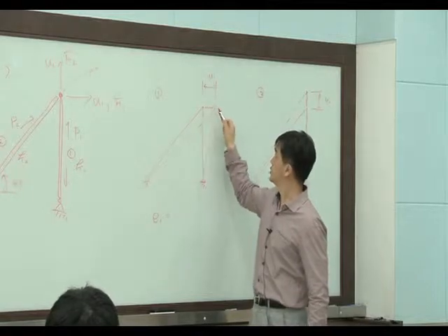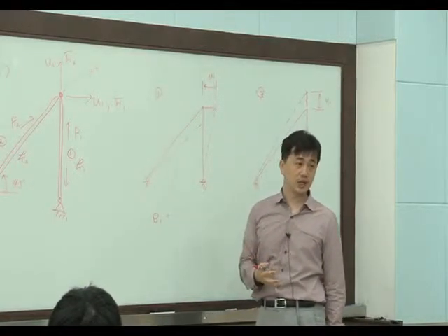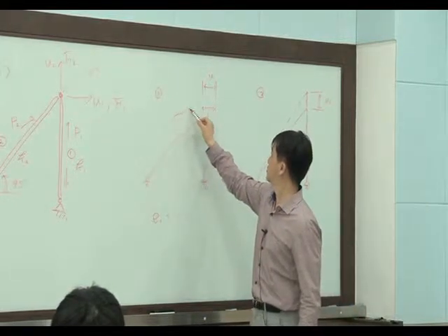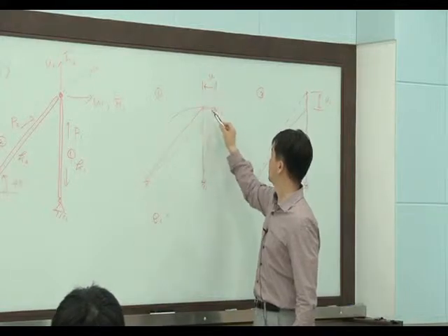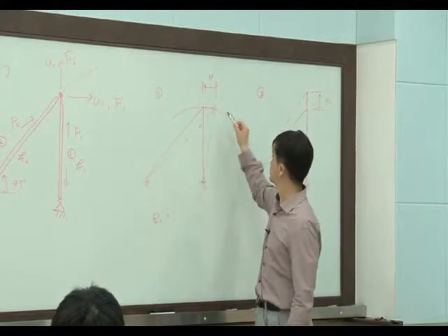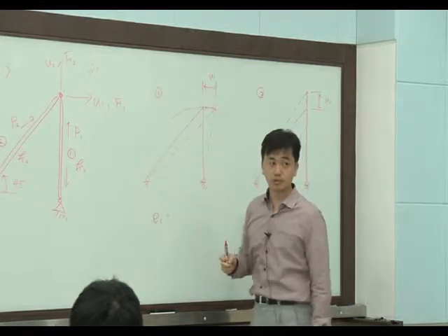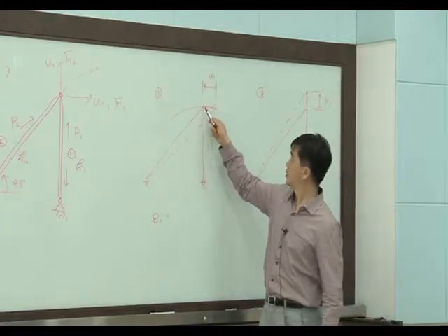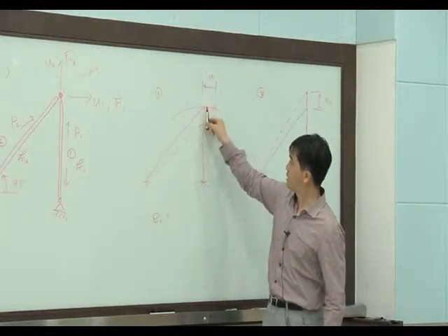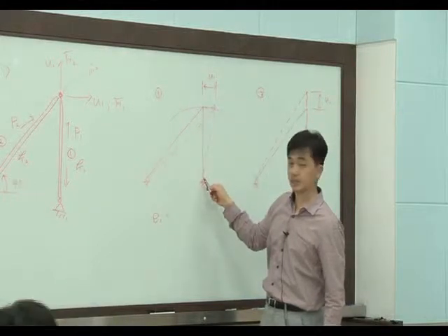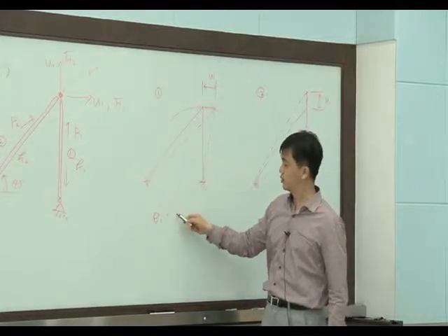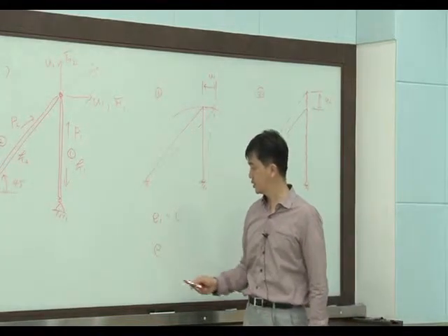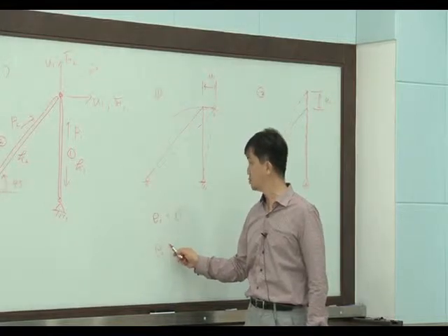For member 1, this movement is just like a rigid body rotation. This is part of the rotation of this member, rotating about this axis. Because we are considering the small displacement assumption, when this bar rotates about this axis, at this point there is no stretch. Okay? How about the stretch of member 2?